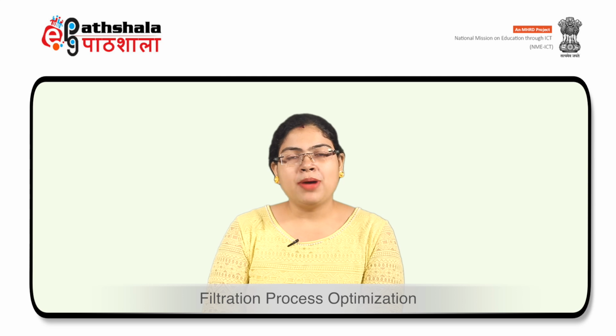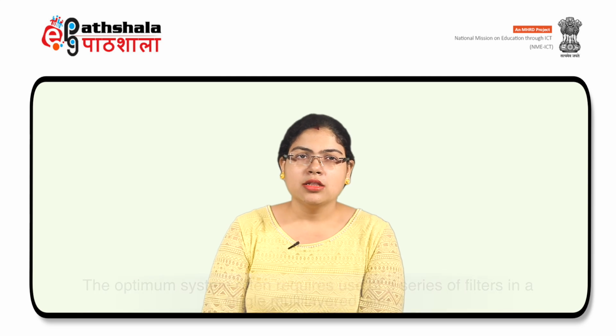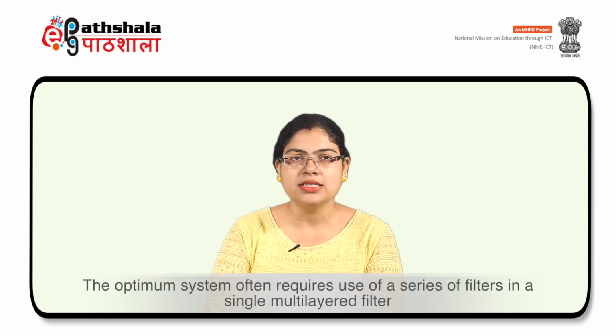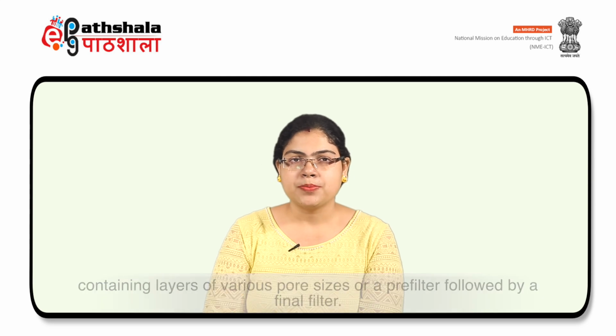Now comes the optimization part, filtration process optimization. Here we will first discuss pre-filter optimization. The optimum system often requires use of a series of filters in a single multi-layered filter containing layers of various pore sizes, or a pre-filter followed by a final filter.